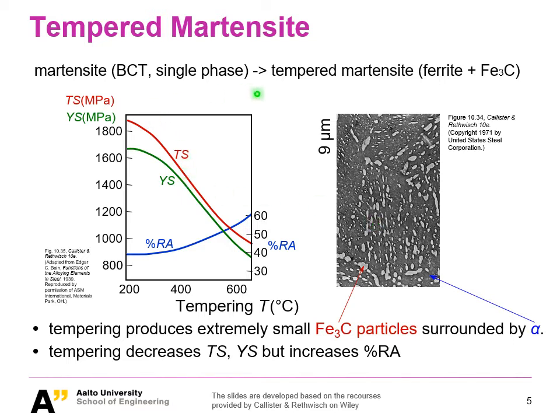And we have already spoken about the influence of tempered martensite on the tempering process to control the strength and also ductility. So basically, they're controlled by somewhat the size of this cementite. As you probably remember, it's always about size, because it's finally related to dislocation mobility, and that is always depending not directly on the size, but indirectly, because it's depending on the boundaries, and the size is directly influencing the boundary.